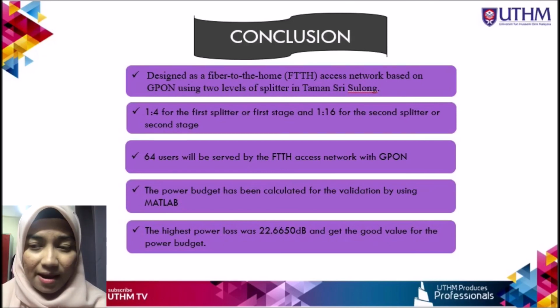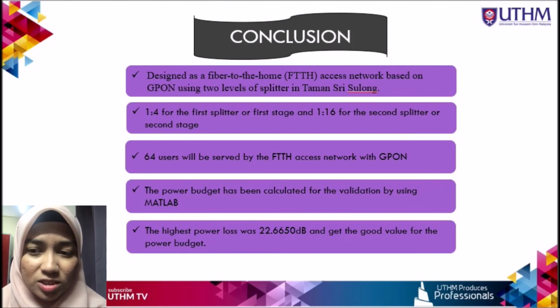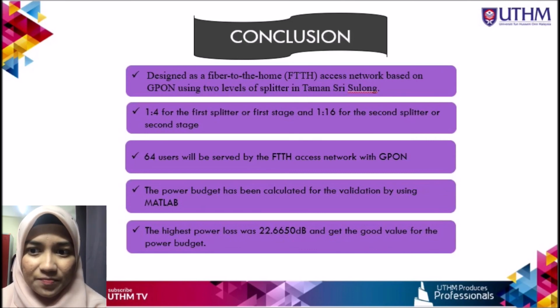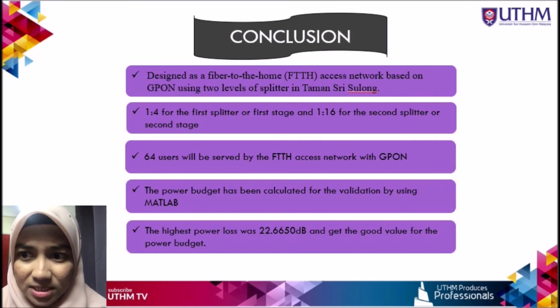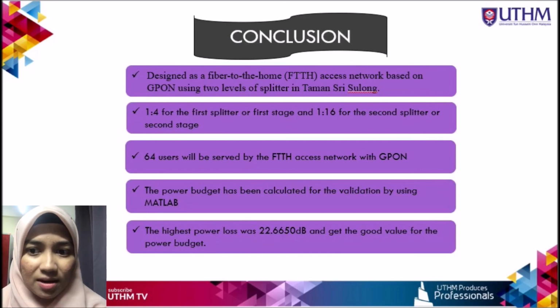Hence, the power budget has been calculated for validation by using MATLAB. The highest power loss was 22.665 dB and we get a good value for the power budget. It means the network and the fiber optic cable link can last with the value of the power loss.